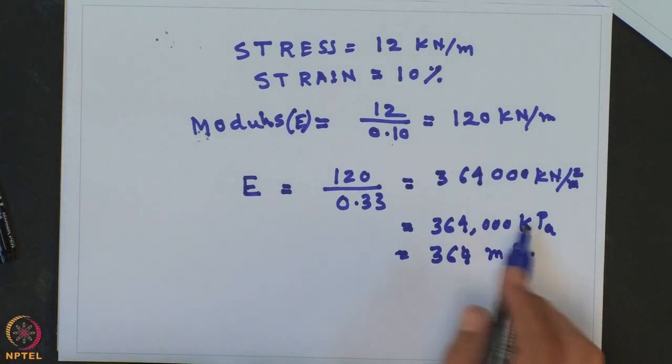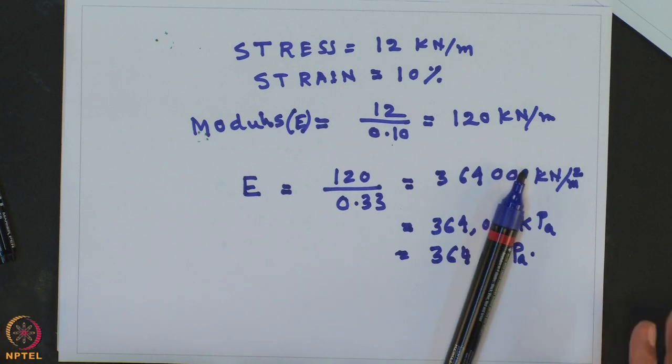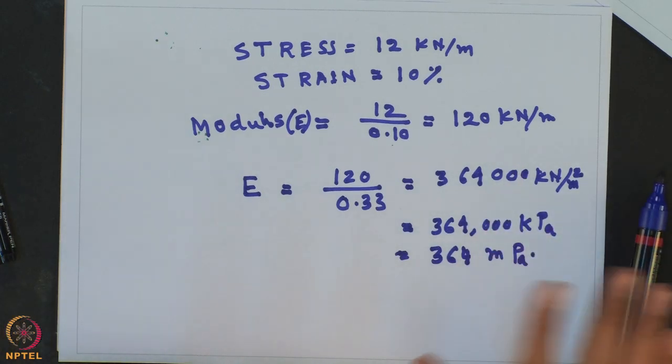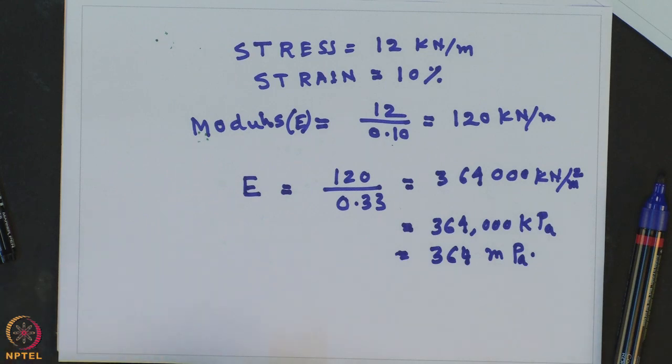So, from the stress strain curve of the geotextile, you can determine different properties of the geosynthetic material, that is initial tangent modulus, second modulus, and the defined types of the modulus or offset modulus, etc. Now, I will give another example for a non-woven needle punch geotextile material.